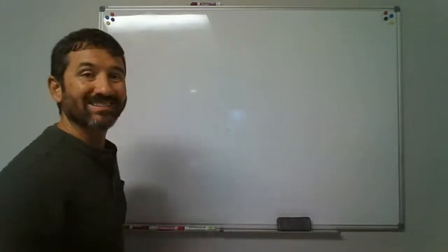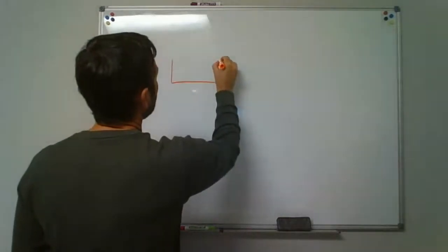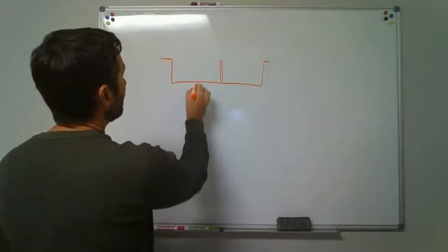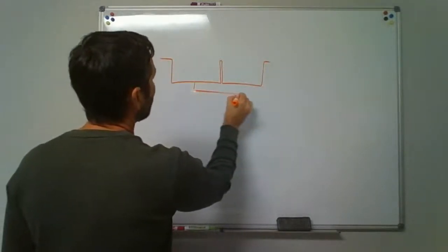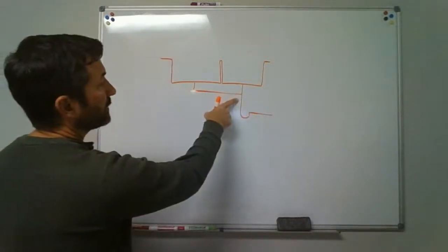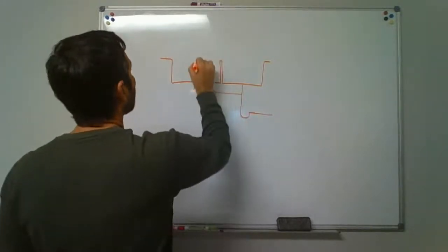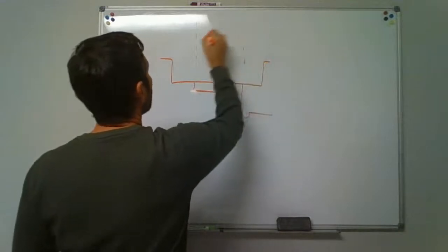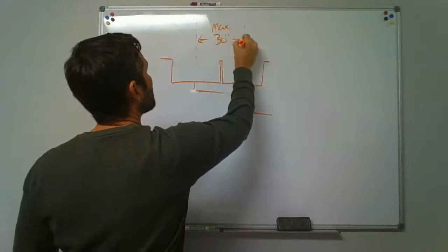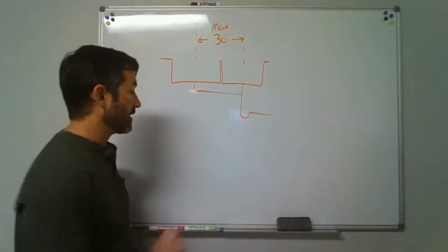But if you're going to do a continuous waste and you have maybe just even your 2-bowl sink, as long as you don't have more than 30 inches of spread, you could come down and have this one tee into this line and be served by one trap, okay? But from the center of this to the center here, that is going to be a maximum of 30 inches between those two right there, okay? And that's what it's talking about on that.